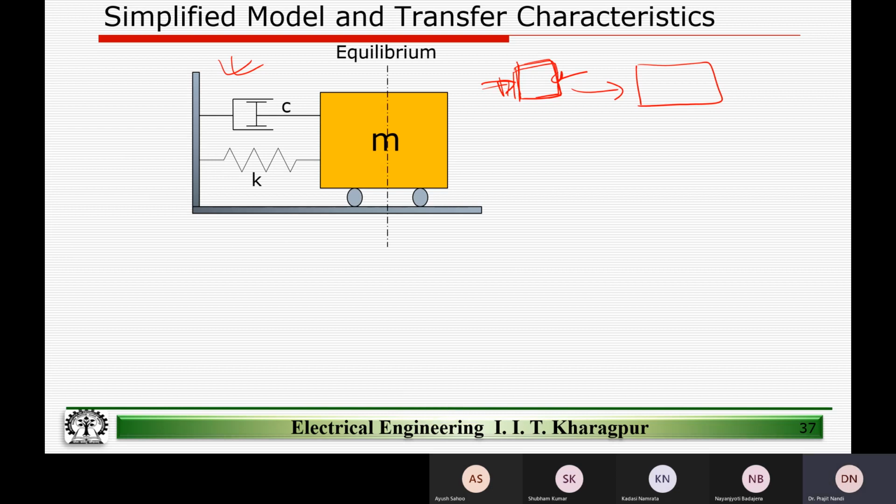So what happens is, we are comparing the spring and the mass and the damper. So this is a damper, this is a spring, not a resistor. It's actually a spring with a spring constant K, and this is a mass M, right? So we can model the complete behavior of the spring and the damper system. We can model the piezoelectric material behavior with the spring and the damper system.